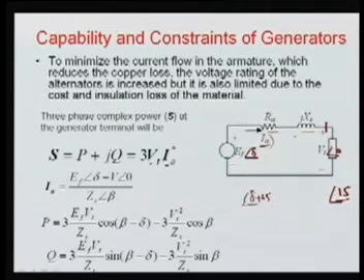So this is basically, with reference to this terminal voltage, this angle delta, that is the power angle. So we can write the current which is flowing as voltage EF angle delta minus this voltage divided by the impedance, which I have written here.